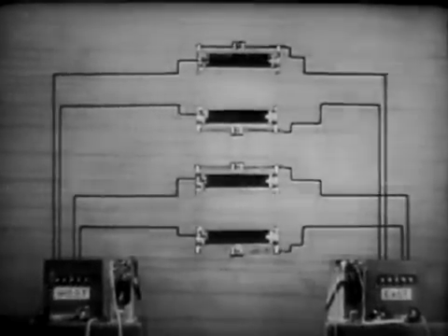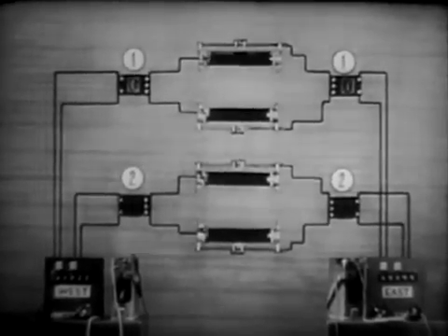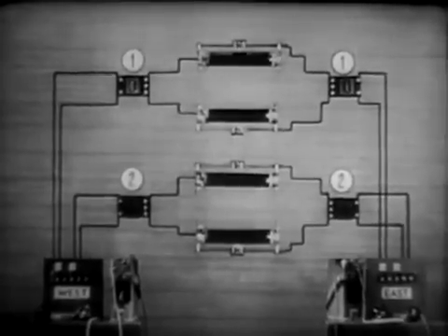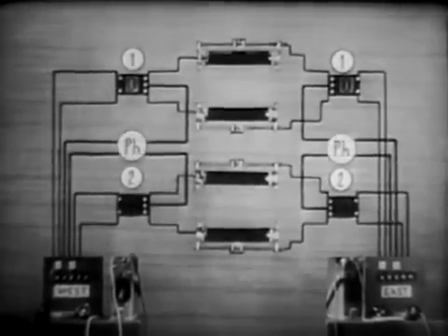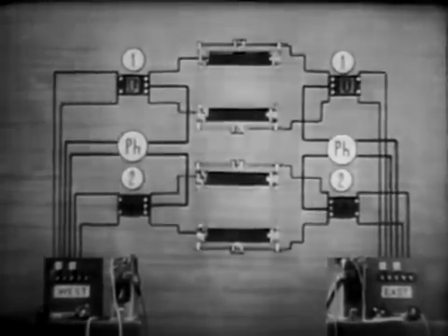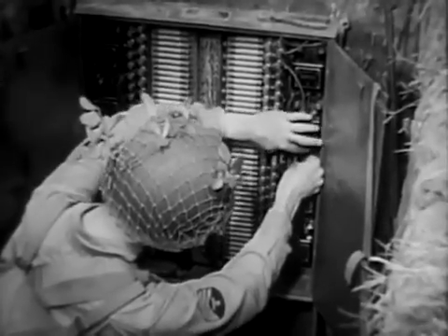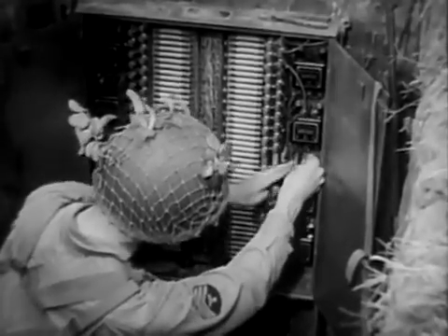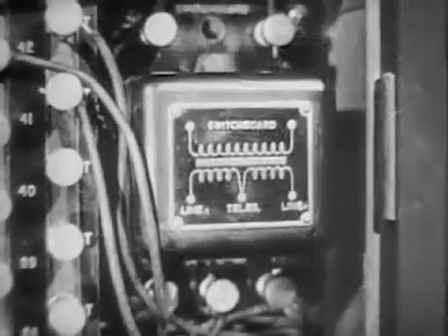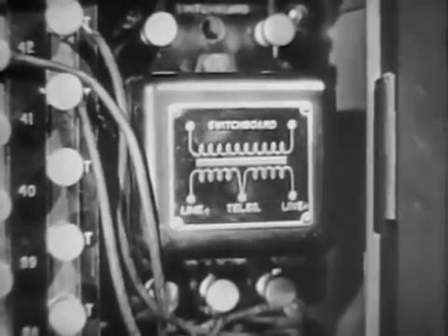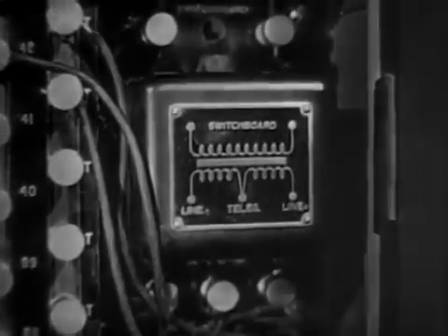The phantom circuit is obtained by connecting repeating coils at both ends of two lines. Instead of using one telephone line and the earth as conductors, the phantom uses two telephone lines. Because simplex and phantom circuits increase the telephone and telegraph capacity of existing lines, the proper use of repeating coils eliminates the trouble, danger, and time of laying miles of extra wire.